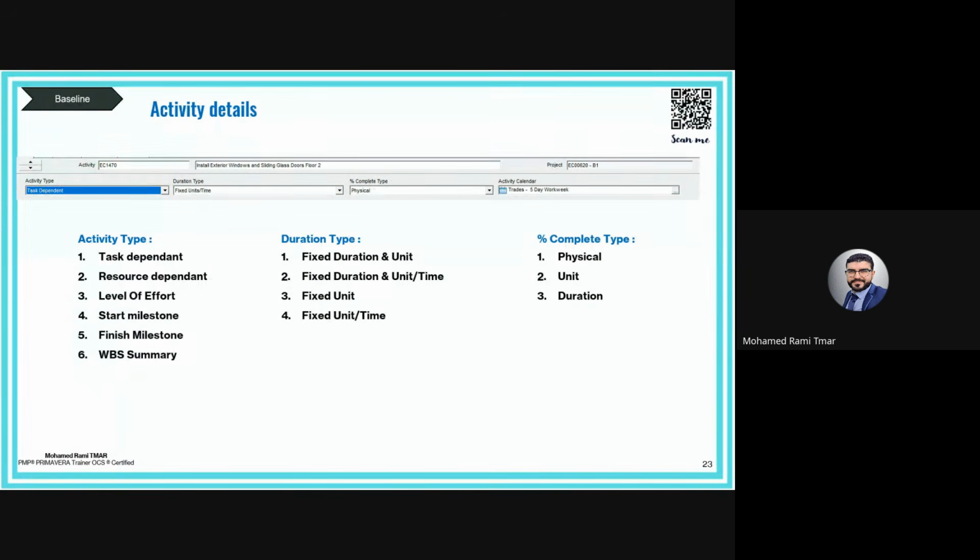So we said unit percent complete is based on quantity completed. Total 100, completed 40, the progress is 40%. Simple idea, progress based on actual installed or production. Okay, this is more accurate and it can be used even in the construction field or any repetitive work or any quantity-driven activities.